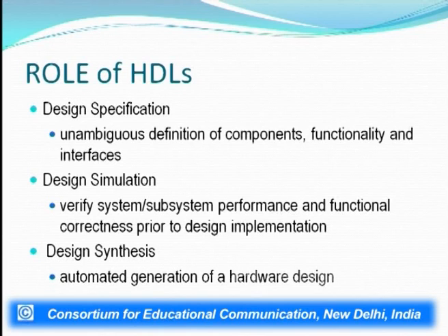Second is the simulation of the design. By simulation, we understand giving signals similar to the real world signals or the target signals which are expected when this circuit becomes functional physically. That is used to verify the system, the subsystem, the performance and functional correctness prior to actual design implementation on chip. And finally, the synthesis of the design, that is the automated generation of the hardware design.